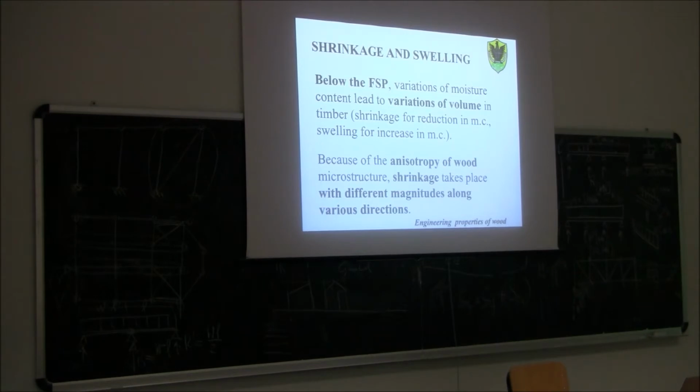So it's not like strength. For strength, if you remember, we said the strength is the same in this direction and the other. Instead, for shrinkage, no, it's much higher in this direction than in the other. And this creates problems of distortion, like this section that you can see. Initially, as you can imagine, this was a rectangular cross-section, and after drying, you see the shape.